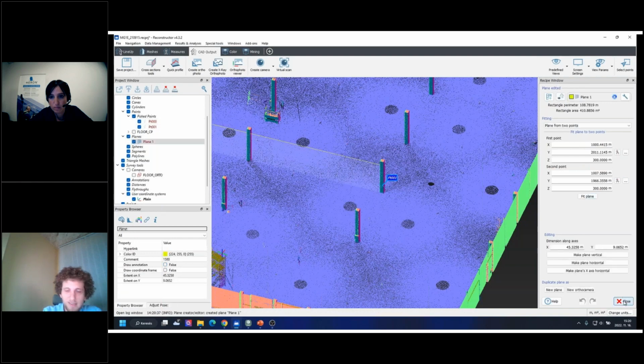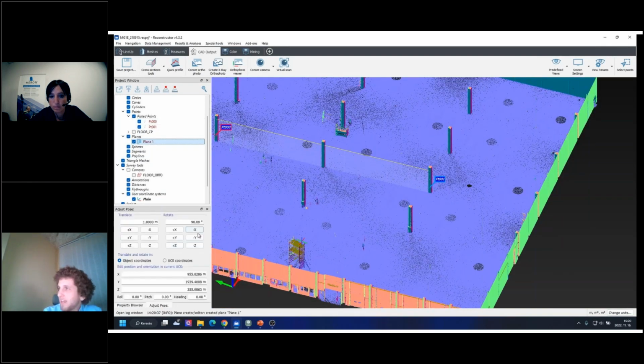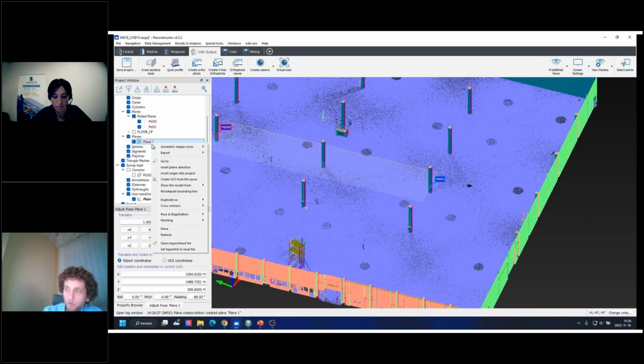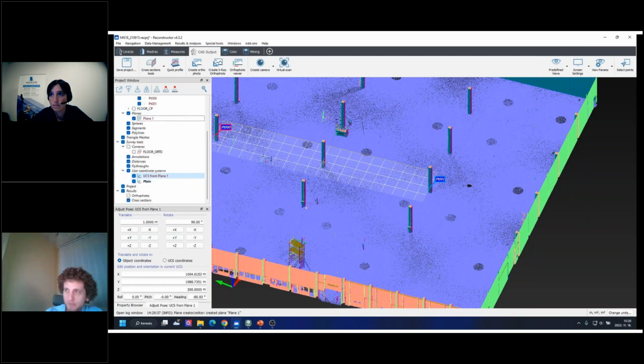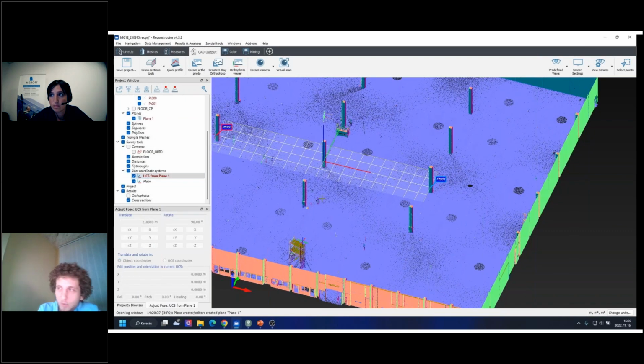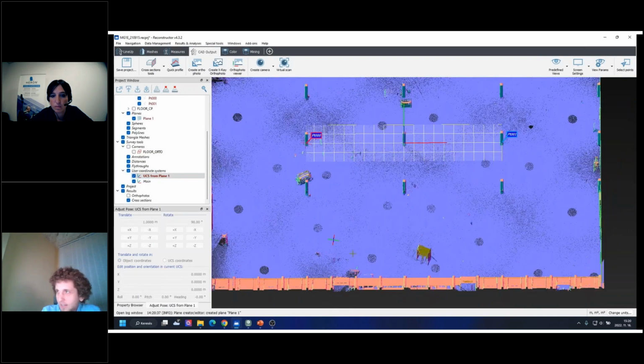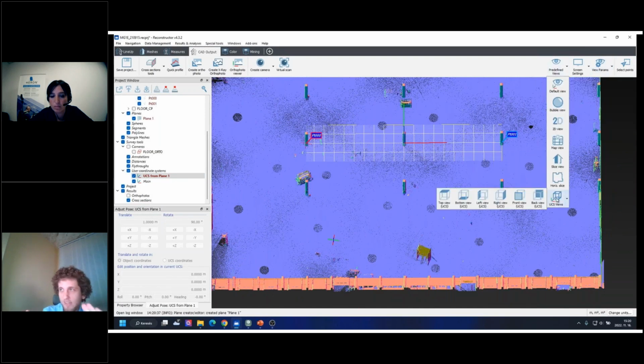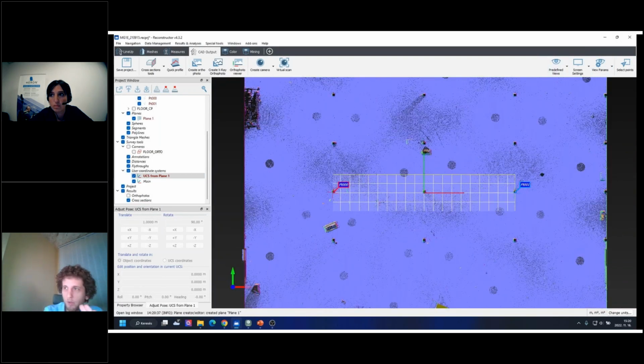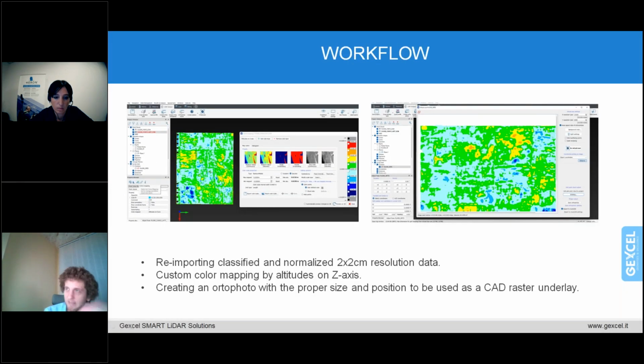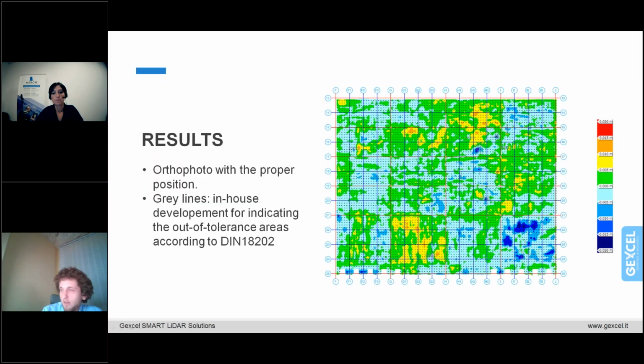Just with the same basis as we used as an example for the facade, having just a few points extracted from AutoCAD, maybe just copy pasting the coordinates or importing them as a CSV list, you can just create a coordinate system, fit onto the geometric features in no time. So in this example, we had the whole site in the national coordinate system, and in 2 minutes, we created within Reconstructor the transformation and the translation for the site coordinate system. And from now on, you can just jump back and forth between them, which is also really obvious, but a very powerful tool.